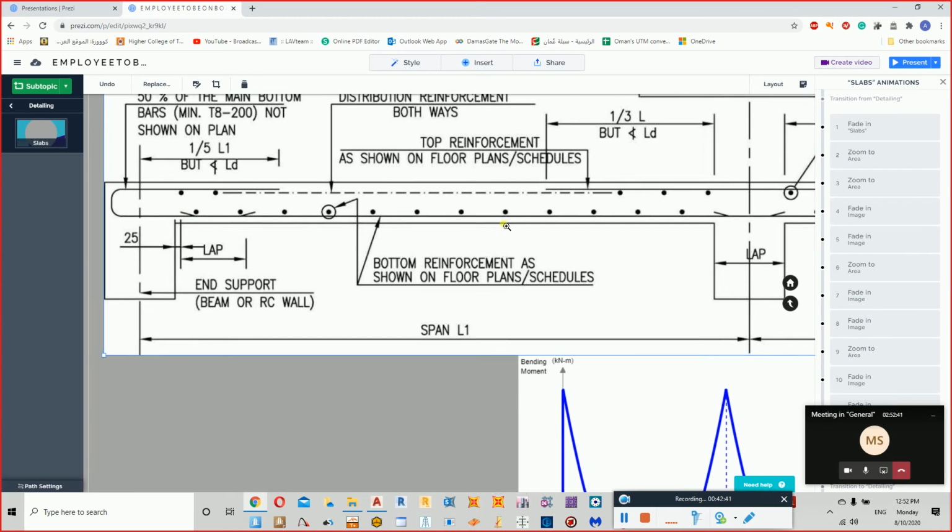this is whatever we call span reinforcement. Span is between the supports. So this is support number one. This is support number two. This reinforcement is acting as the span reinforcement. The bottom one is considered to be the short span. The circle ones are considered to be the long span.